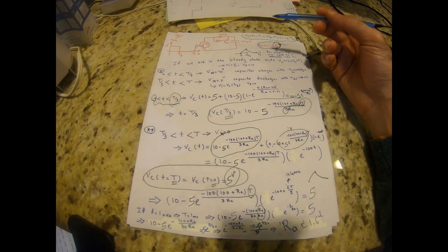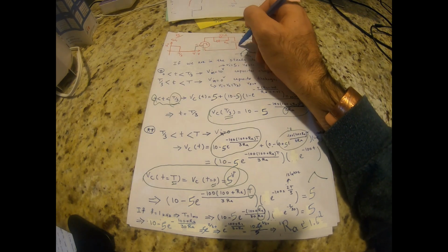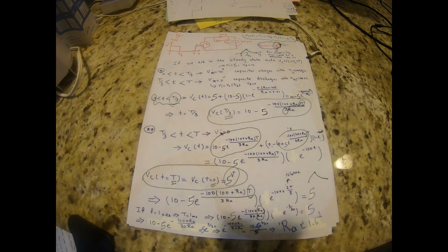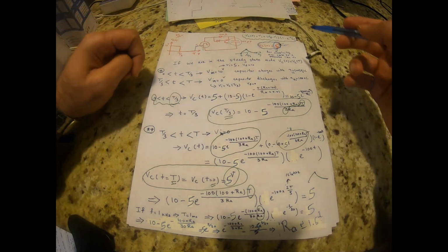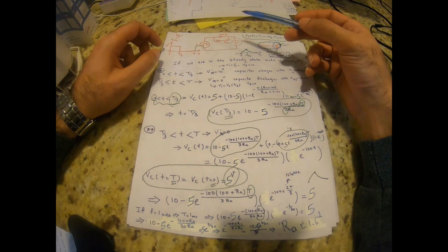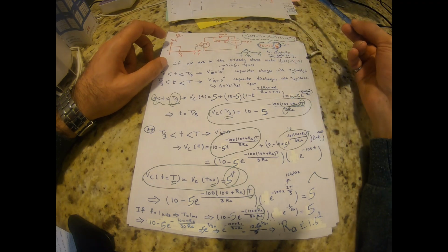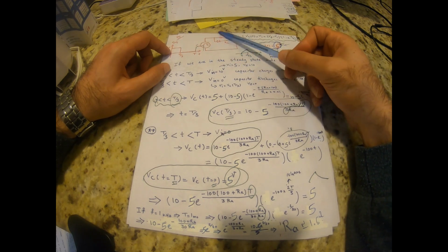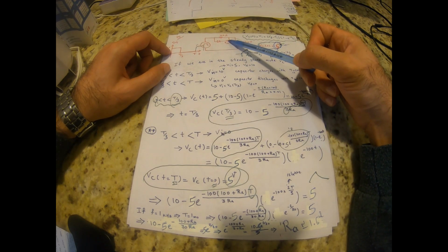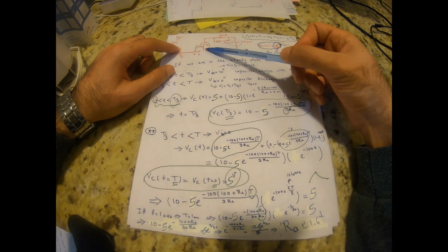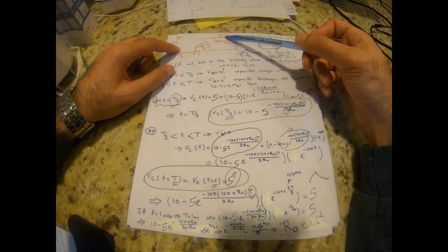So how did I do that? What's the concept of volt-second balance? It means that you get charged the same amount that you get discharged. Now, in this case, again, I use the general formula for the capacitor voltage of an RC circuit. Similar to the previous question we solved, if the voltage is positive, we have two resistors in the circuit. If the input voltage becomes 0, the capacitor is going to discharge. We only have the 100 ohm resistor in the circuit.